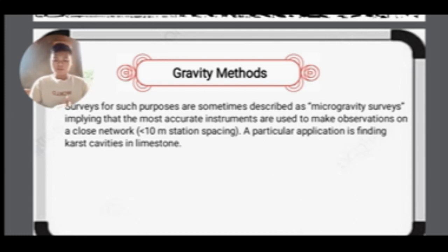The intensity of the Earth's gravitational field may be measured using gravimeters. These are in effect extremely sensitive balances in which the very small movements associated with variation in gravity between successive points of observation are magnified to readability by mechanical or optical devices.